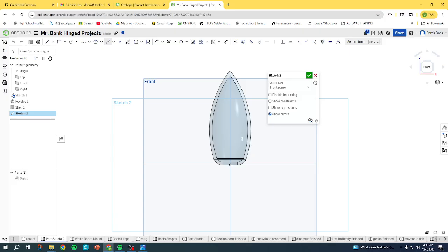And you're just going to draw one, because then we're going to make a mirroring of it. So you can sort of pull and play with a type of fin style. I'll come back, because what you're going to have to do is complete this shape. You don't really want to use a spline for it. Hit escape and then use a straight line to connect the two endpoints of that shape. You'll see it'll turn gray.